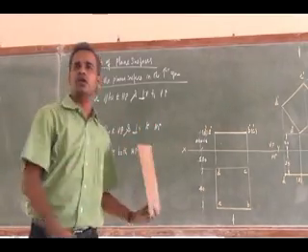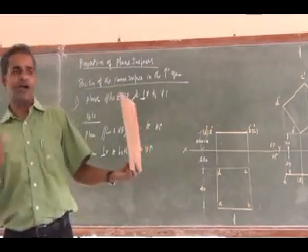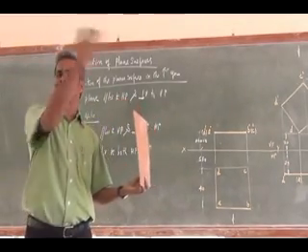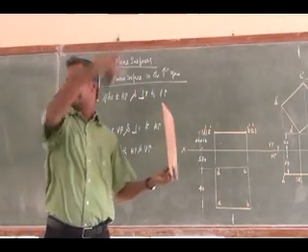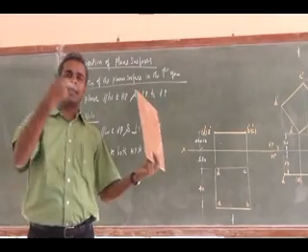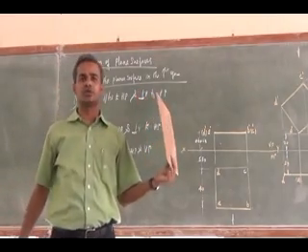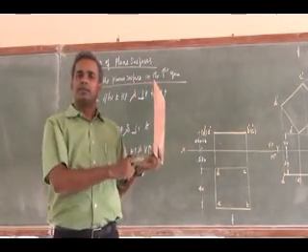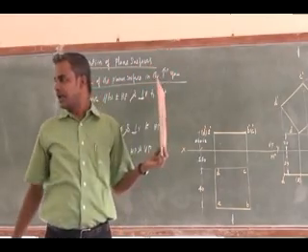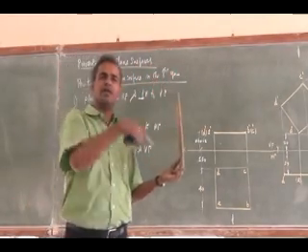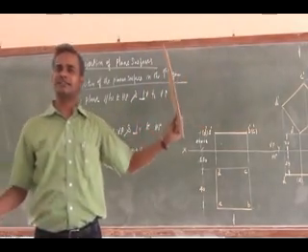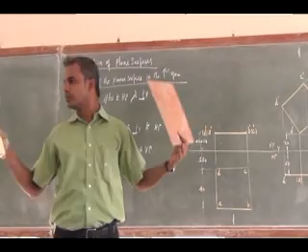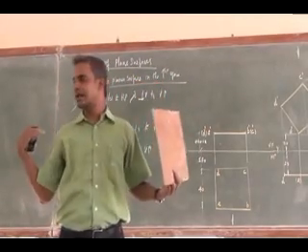But in both front view and top view, I don't obtain the true shape. Where will I obtain the true shape? Wherever it is parallel, to whichever reference plane it is parallel. So I will have an auxiliary plane, and on the auxiliary plane I will get my side views. The plane is parallel to the auxiliary plane, so I will obtain the true shape on the auxiliary plane. That is, the auxiliary plane will hold the side view, either left side view or right side view.